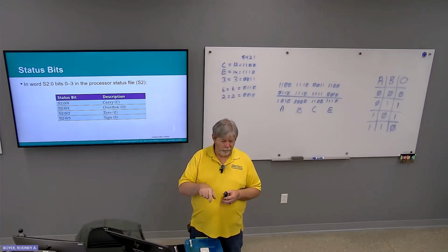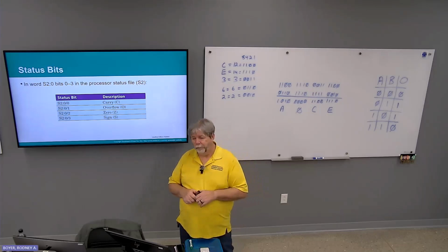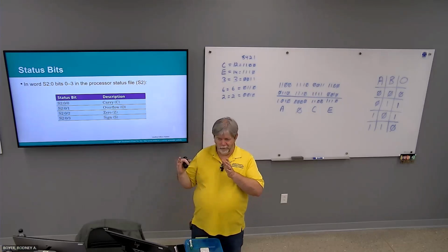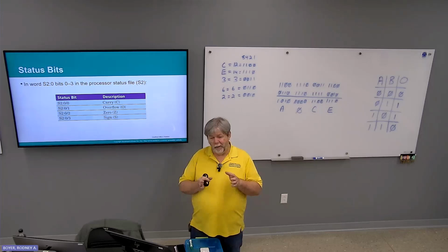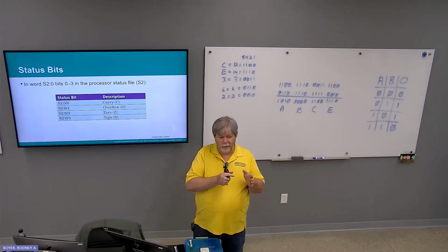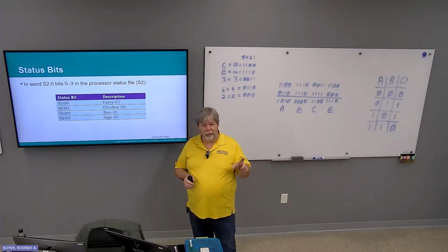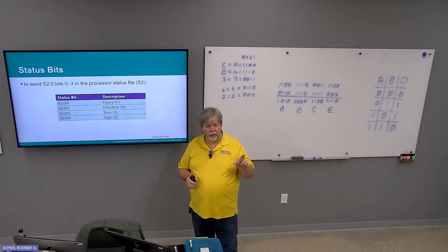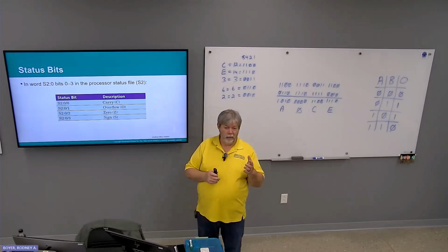On for 4, off for 4, on for 8, off for 8, and so on. Those lower bits switch so fast that they're basically unusable. But if you get up around 12, 13, 14, then you can use that bit to toggle a light on and off, or a buzzer or something for an alarm. That way you don't have to burn 2 timers, time on and time off.